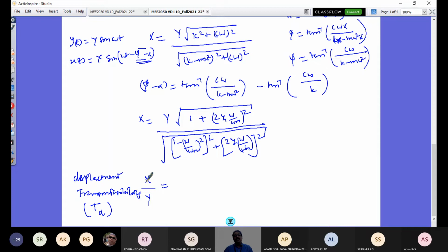So if I give this and there is zero displacement, that is what is the best vehicle. You would have 100% isolation that's possible in your vehicle, right? So what is preferred for your comfort? What is preferred for comfort? Comfort of a car, this x by y should be tending to 0. So when can it happen is what you'll understand in a while. And that would happen when omega value is much, much greater than omega n.